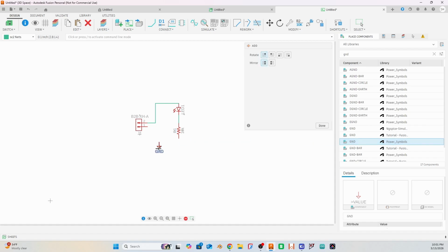And just double click on it, then grab one, put it right about there in the ground, and then put another one right here. Click OK, and then type R or just click net right there and wire the whole thing up. And voila, this is the schematic. Essentially it's just the circuit that glues all the components that you need together.